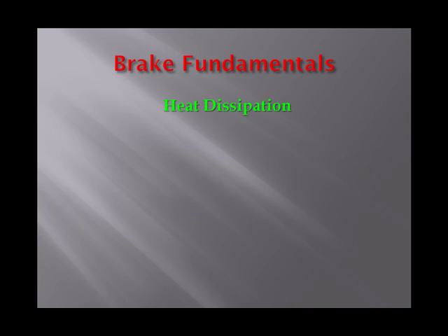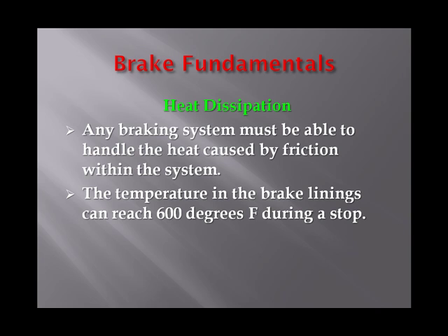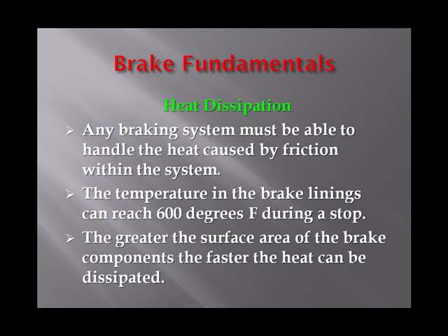Heat dissipation. Any braking system must be able to efficiently handle the heat caused by friction within the system. The temperature in the brake linings can reach 600 degrees Fahrenheit during a stop. This is tremendous heat and is created by rubbing. It must be directed away from the pads and rotors or brake shoes and drums and absorbed by the surrounding air. The greater the surface area of the brake components, the faster the heat can be dissipated.